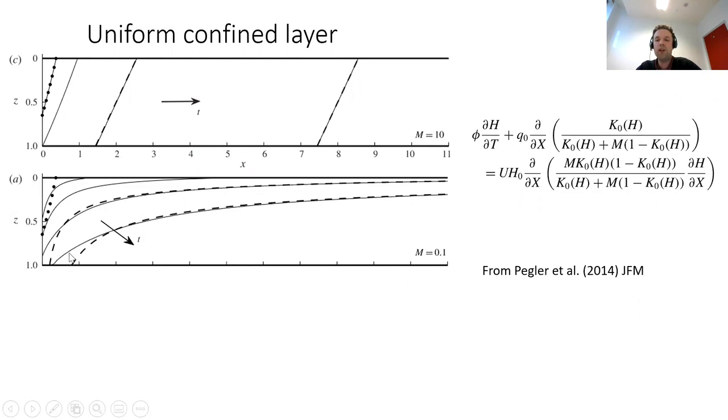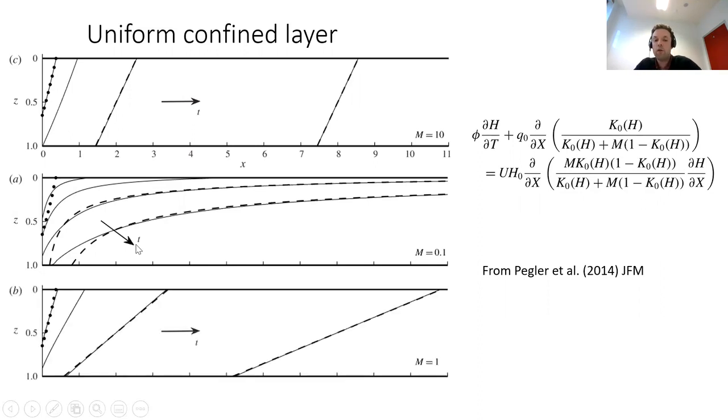You get one finger forming because buoyancy suppresses the formation of other fingers, which would arise owing to the instability of the input of a less viscous fluid. If you didn't have buoyancy, you would have lots of fingers. And then for equally viscous fluids, you get a singular behavior between the two regimes, where the interface moves downstream with constant velocity and spreads out with its extent growing like the square root of time.